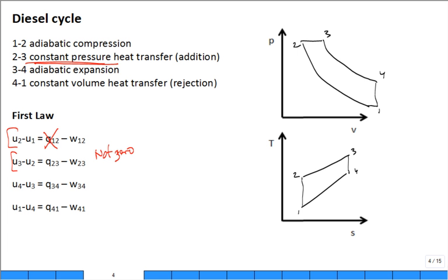All right. So how do we calculate that boundary work, work 2 to 3? Integral PdV, and we like that. So the work 2 to 3 is the integral PdV from 2 to 3, and so this pressure is a constant, makes it a very easy integral, and so we're left with the pressure times V3 minus V2, or you could put, it's the same pressure, 2 is equal to 3, so when I multiply by V3, I put P3, and when I multiply by V2, I put P2.